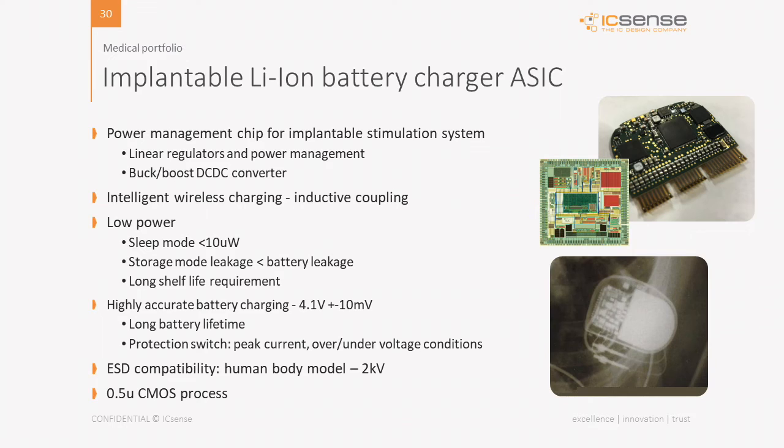Also, with respect to low power optimization, we have put a lot of tricks in to keep the sleep mode as low as possible, and also to keep the storage mode leakage below the battery leakage, so that if the chip is on the shelf for many years, it's still operational when the chip must be implanted within the body. Also, ESD compatibility is key for that.